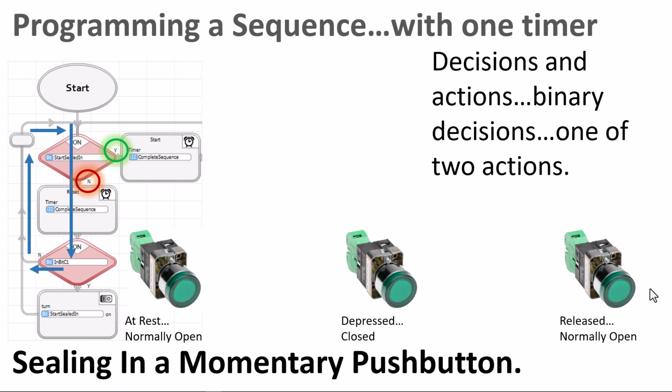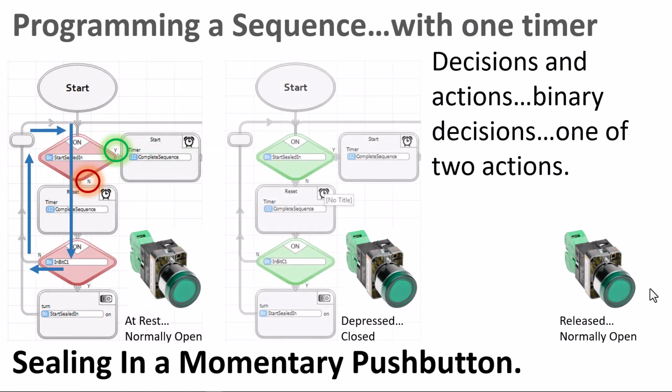Is sealed in on? No. Reset complete sequence. Is the push button pushed? No. Go back to the beginning. Is start sealed in on? No. Complete sequence reset. Is input bit C1 the push button on? No.